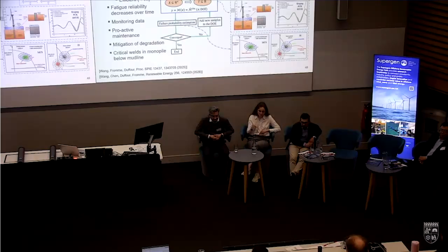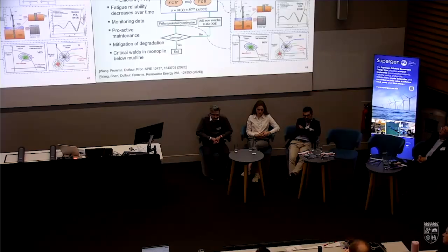The outcomes are probably not that unexpected: the fatigue reliability decreases over time. But if we look at some of the critical weld locations in the monopile below the mud line, what this model allowed us to do is look at how, if we have monitoring data and consider proactive maintenance, we can mitigate that degradation. For details of the model, I would refer you to some of our publications here.